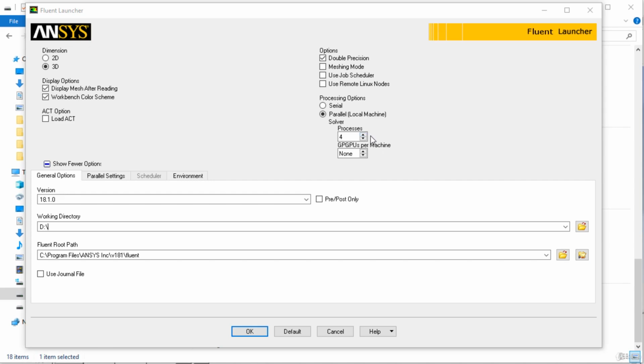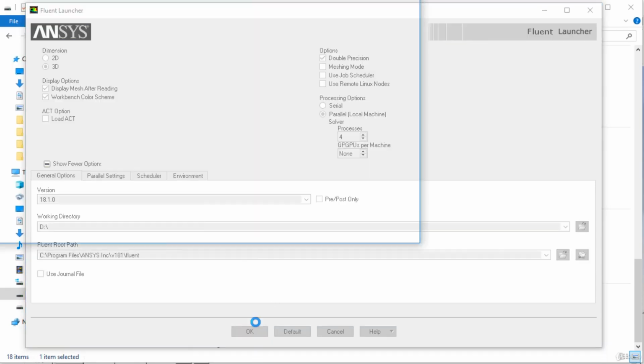So in your mesh, this can be slightly less, it may be slightly more. So maybe you have 1.2, maybe 1.1. It doesn't matter, but it should be on the same scale. On the overall looks of the mesh, they should be the same as shown in this tutorial or the workshop. And then click on OK.